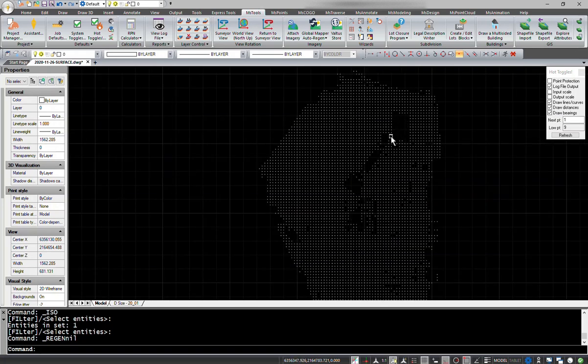And what I'd like to do is generate a surface, and what I want to pay attention to is how long the triangle sides are going to be when it generates the surface. And it's a nice idea to set the triangle length, or the maximum triangle length, to about double what a typical distance within your data set is. So I think what I'm looking at here is there's a big void here, and I'd like to make sure that my triangles can make the jump all the way across.